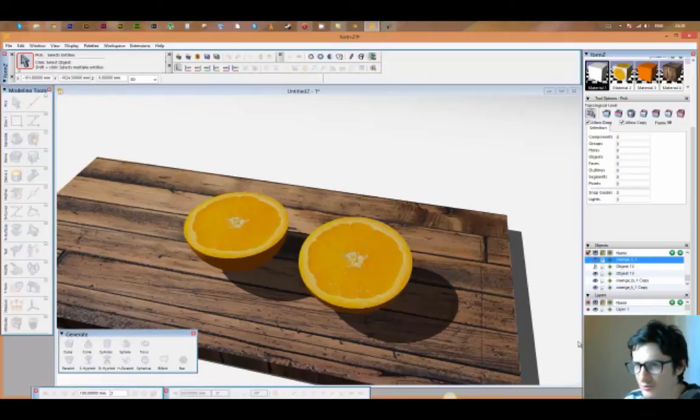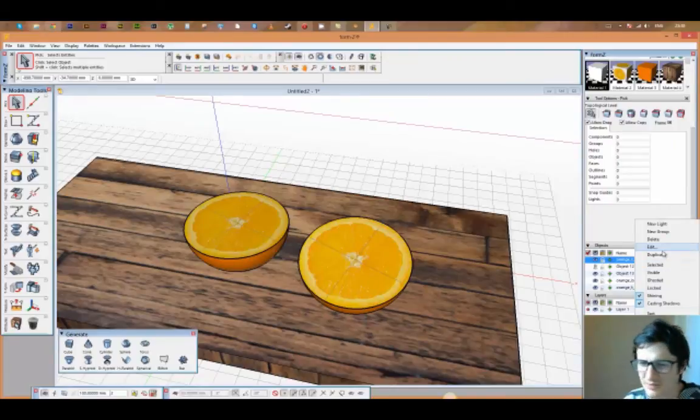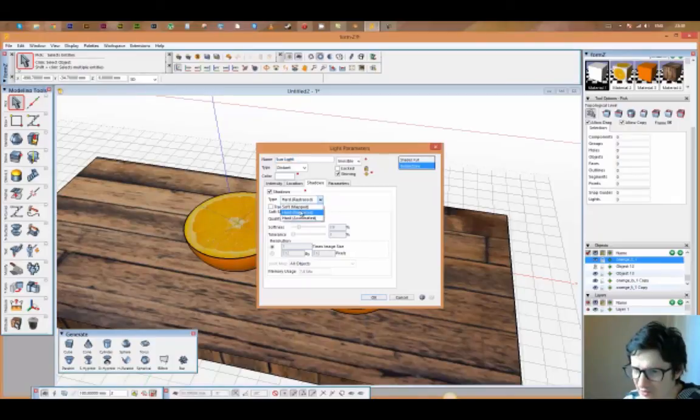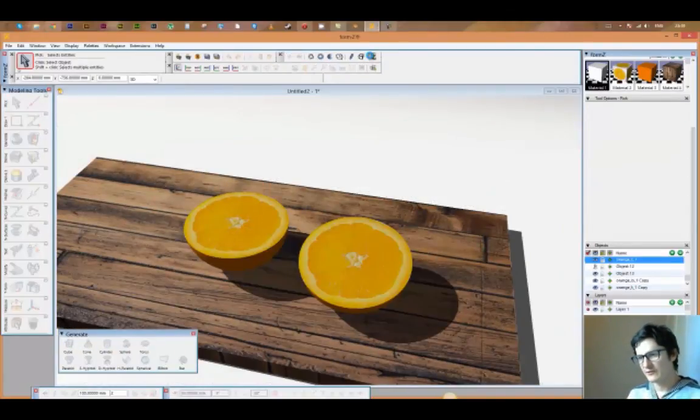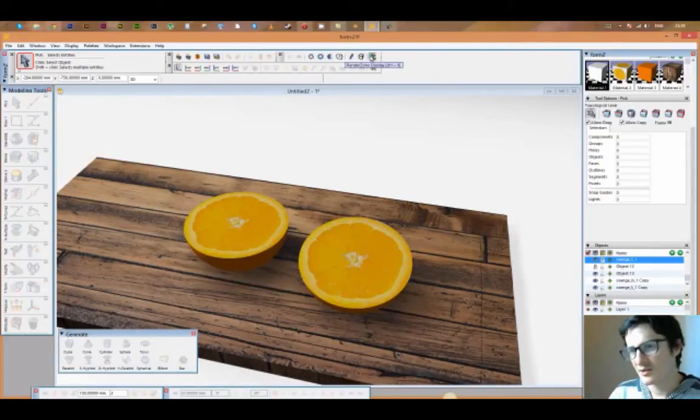So I tend to go for a much softer shadow, and there is a sweet spot there I think that works, which is around soft map shadows and high quality and a smoothness of something around there, just to soften up the edges of those shadows. That's better, right? Okay, now it's a matter of finding a view that's a bit more dramatic than what we see here.